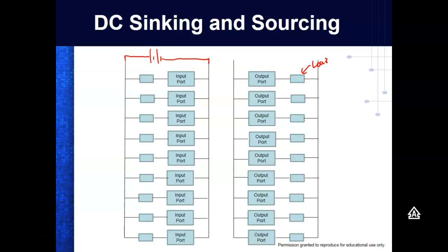Hopefully I reversed it. Yeah. So here, inside the PLC, its port is using the minus, and then the inputs are using the plus. This is a common connection right here that goes down to all my input devices. This term came from digital, but this is the way it works in PLCs.